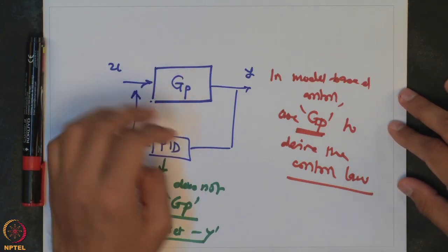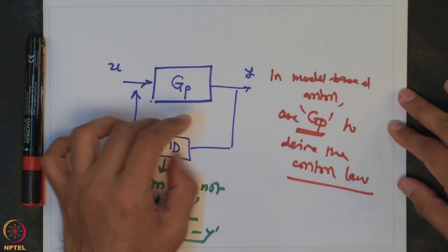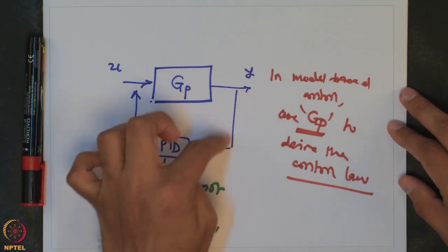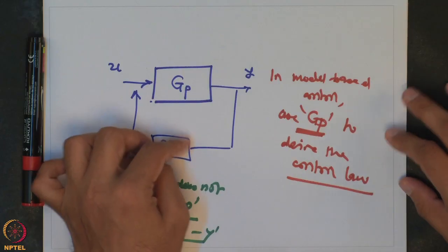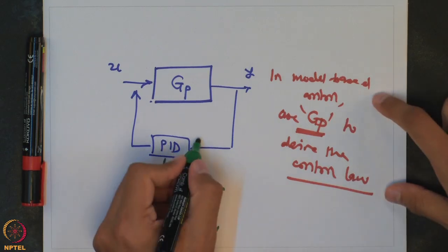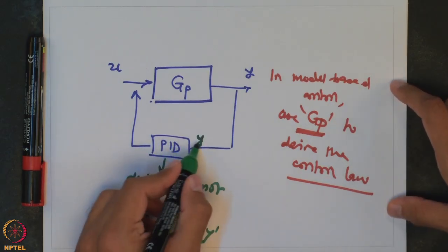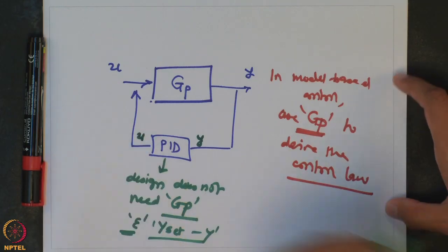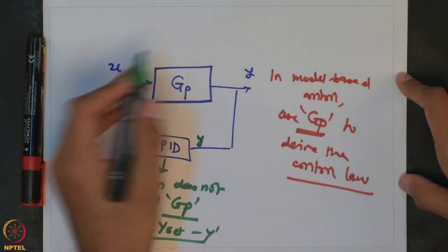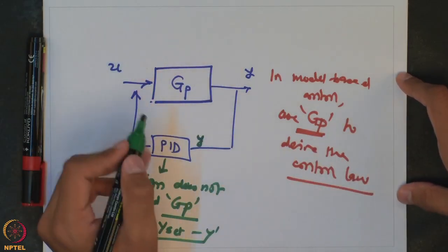In terms of control, it is exactly the opposite. In control, the input to the controller, let us say a PID controller or a model based controller, is the output of the process. So, if you look at the control system, your input is Y and the output of a control system is the manipulated input. So, it is exactly the reverse map of your process.